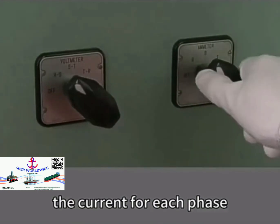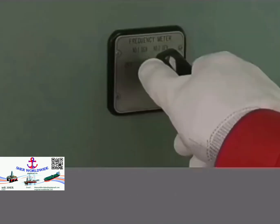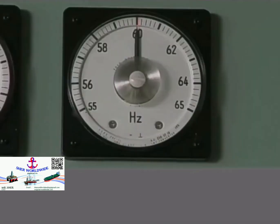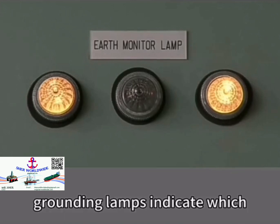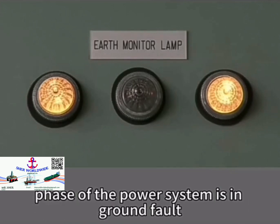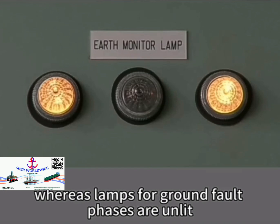The current for each phase. And the frequency. Grounding lamps indicate which phase of the power system is in ground fault. Lamps for normal phases are illuminated, whereas lamps for ground fault phases are unlit.